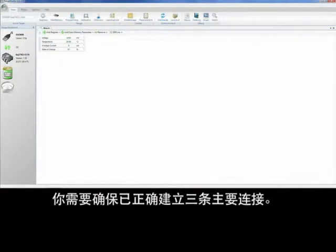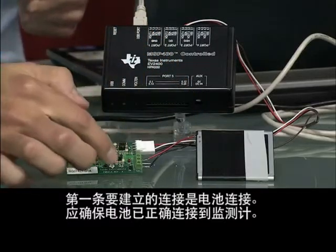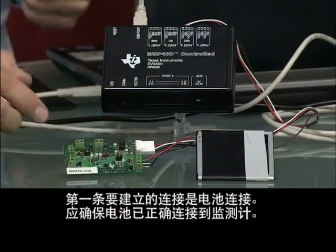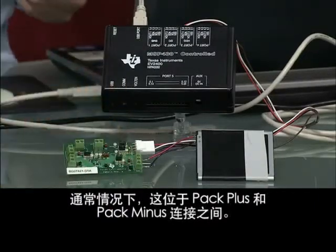There are three main connections that you want to make sure that you have done correctly. The first one is you want to make sure that you have your battery, and that it's connected properly to the gauge EVM. Typically this is going to be between the PACK+ and the PACK- connection.